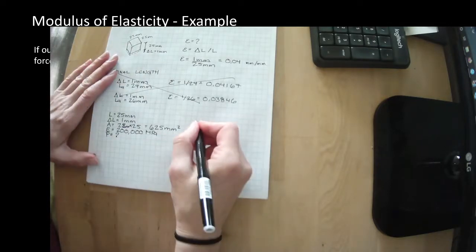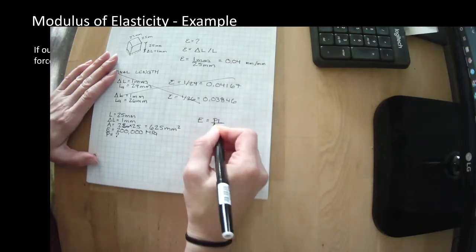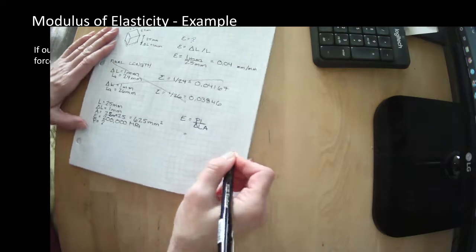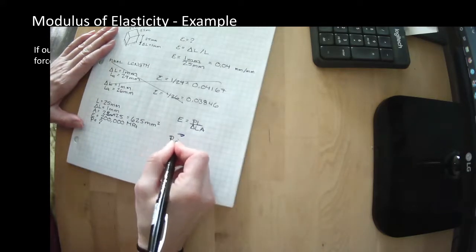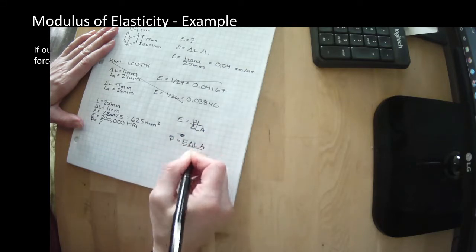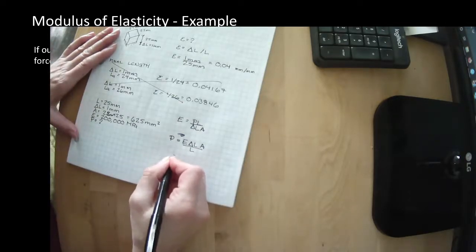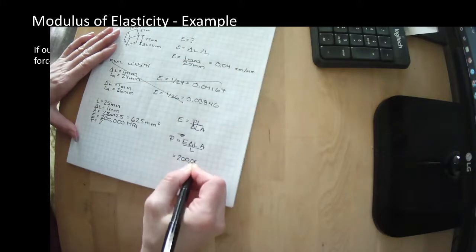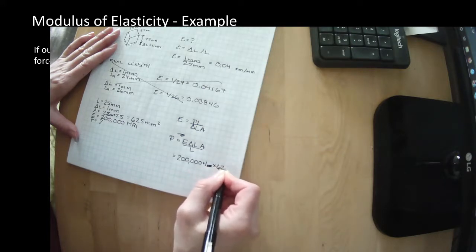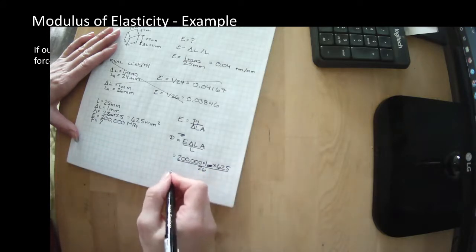We know that E equals PL divided by delta L A. We want to rearrange this to find P. P equals E delta L A divided by L, or P equals 200,000 MPa times 1 millimeter, I'm not going to put the units in, times 625 millimeters squared, divided by our original length, which was 25 millimeters.